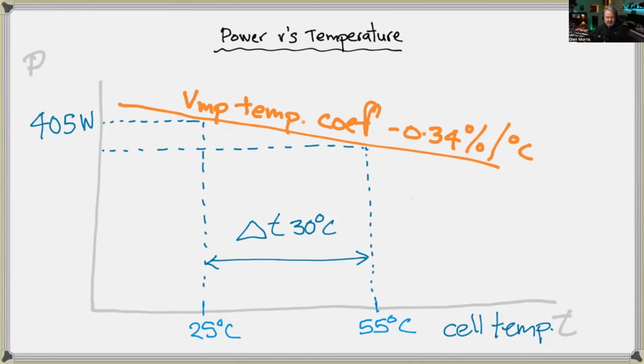So to actually have a 405 watt panel produce 405 watts, it would probably have to be sitting around -5 degrees ambient. So just because of the amount of heating that you'll get even in a really cold place with the sun on the panel, it'll rise. So it's unlikely that you would get this in anything but sort of snow conditions.